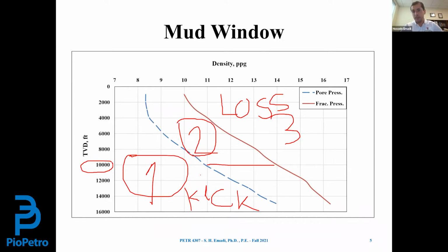Obviously, the more additives we need to add to the drilling mud to make it heavier, and the more additive we add to the drilling mud system, the more expensive the operation becomes, and the more overbalanced we become. On top of that, the more overbalanced we become, the less rate of penetration we get. So we tend to be close to pore pressure, but not too close.